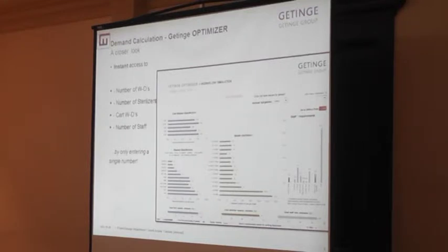Because this is with a constant flow of goods to the CSSD, and that's never happening. We have ups and downs to the CSSD from all the departments, and this is considering a constant flow of goods. That's why we always take the figure from 3.5 up to 4 in this case. So washer, a big sterilizer, for example, 3.3. Okay, 4 probably. And I can take a different kind of sterilizer if that is closer. So I normally want about half a machine extra.